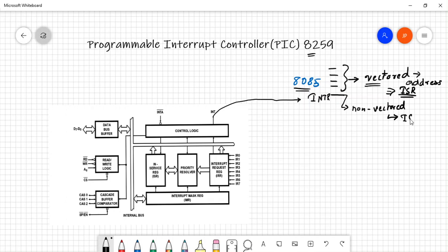There is no specific address for the INTR pin, which is a very useful functionality because you can connect multiple devices, right? Depending upon the device that is interrupting, you can give the corresponding address, whereas in the other hardware interrupts, you can control only one device. Let's say your processor requires multiple devices.